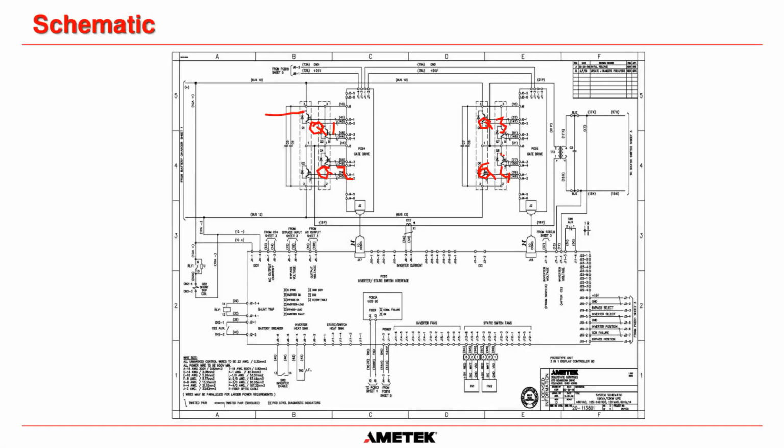And what we would do is we would take the positive down through here. It goes down up to this transformer here, and then back up through this IGBT. It's very difficult to see on this, but we get back to just Q1 and Q4. So it goes down that way and out that way. And that would give us our negative pulses on that portion there.